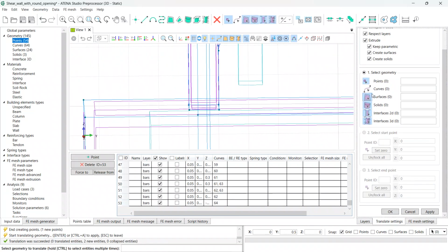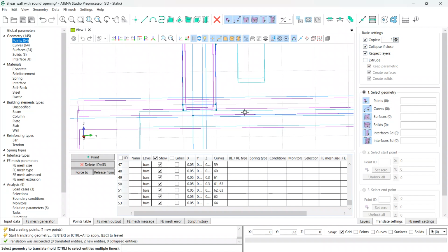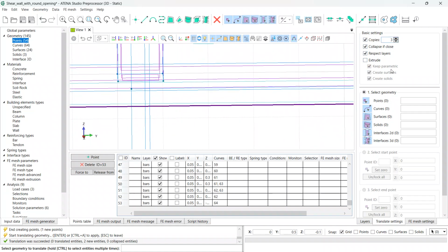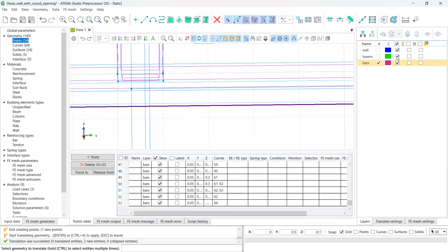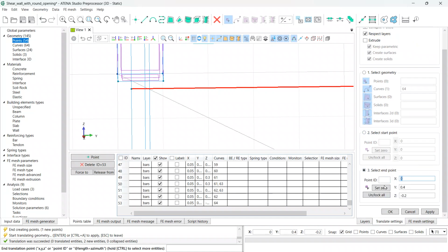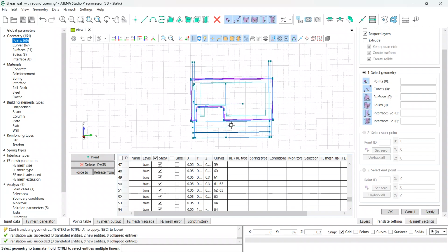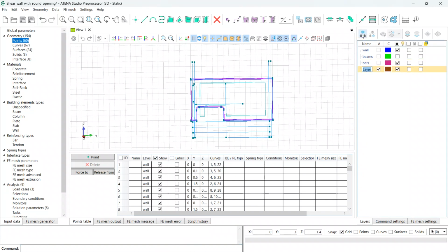And the first bar at the bottom beam that we created, we are going to copy 3 times below the first one. And sometimes other geometry is a little bit interfering, so we can switch off layers that can help us. Yeah, so now we have the first part of the mesh, and we create another layer for this mesh reinforcement, which will be helpful later on for assigning of materials.